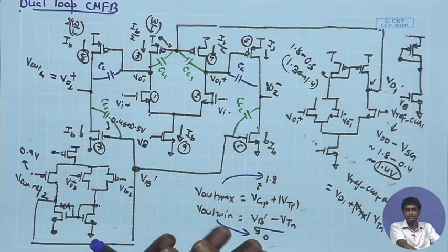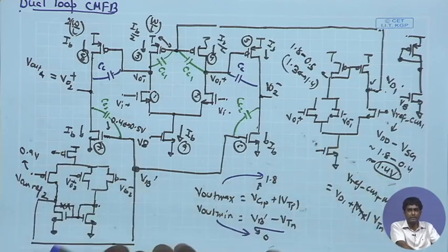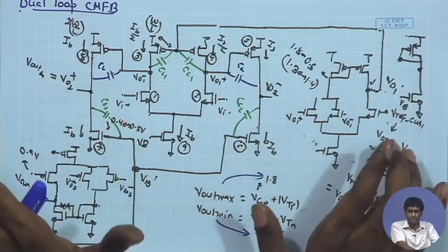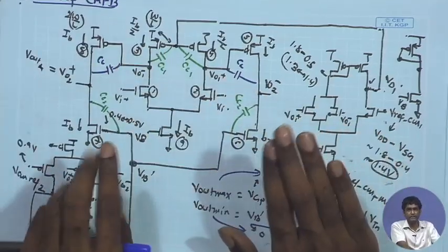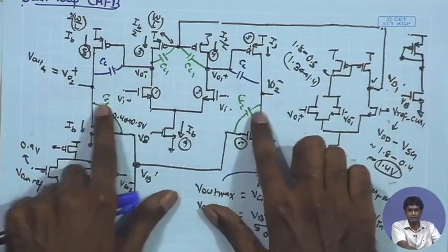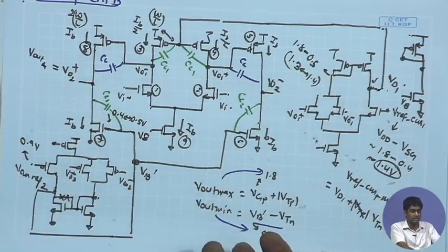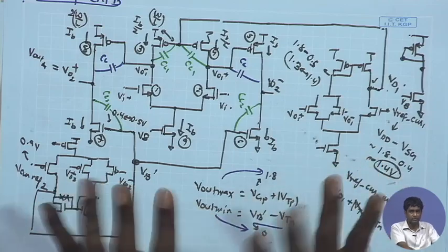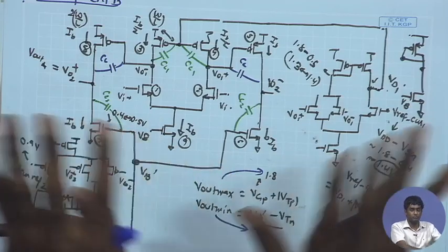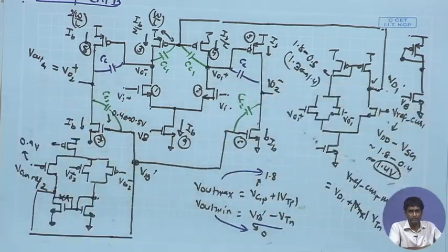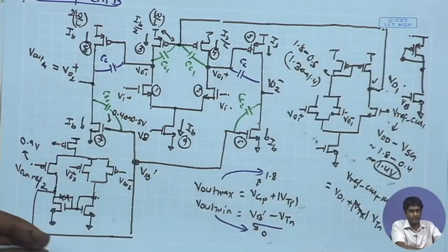In some cases, you want to be aggressive and in others conservative. So, you will try to compensate the differential loop also for the worst case, that because of the parasitic effects at higher frequency, the beta approaches 1. That will be the worst case, and therefore, I will consider the loop gain of the differential case also to be GMRO square, then the CC value will be large. But you can take advantage that for the differential loop you have the beta factor, and that is reducing the open loop gain overall. The overall loop gain is getting reduced by the factor of beta, and hence you can afford a smaller CC for the differential case. So, that will allow you to compensate the differential loop separately and the common mode separately.